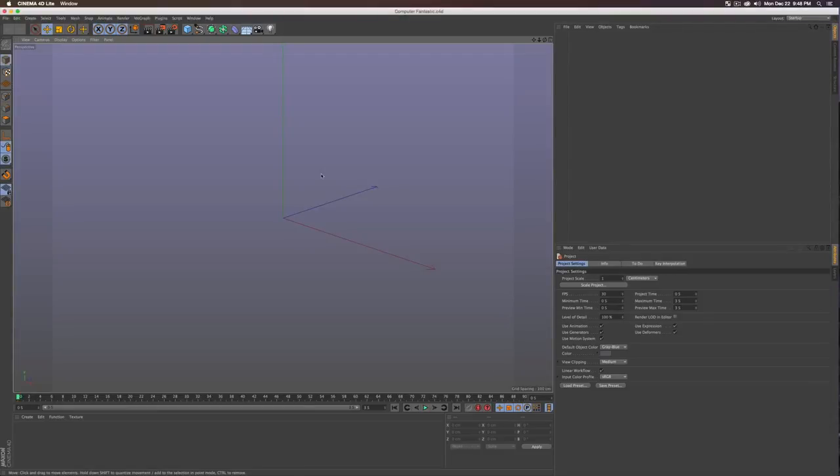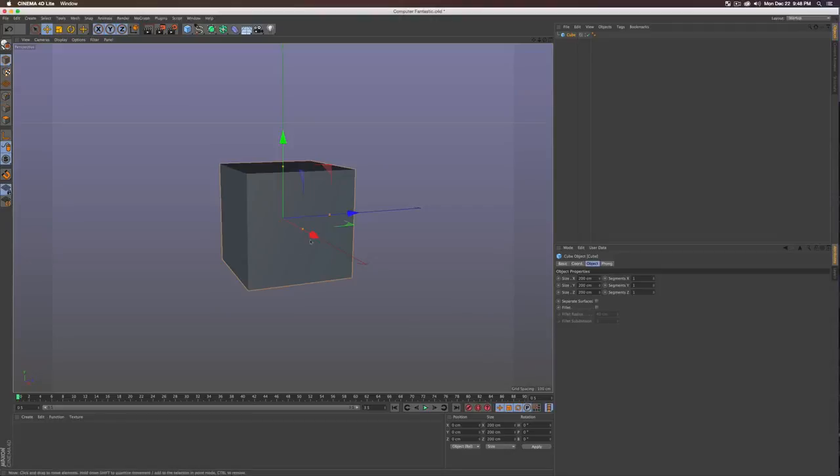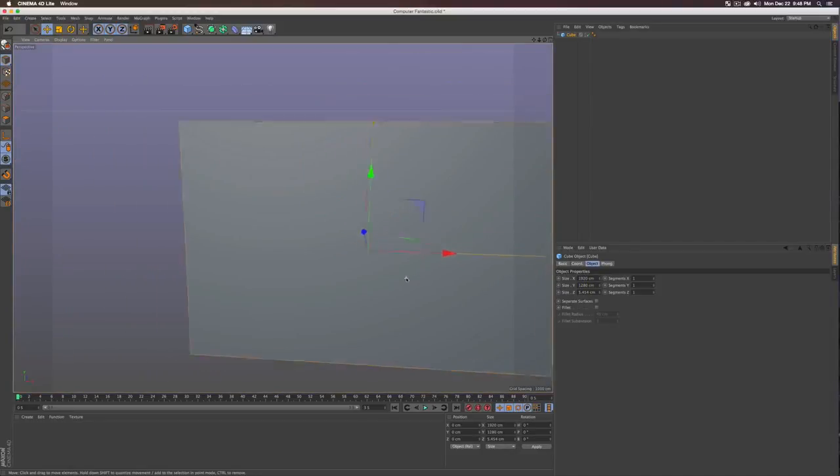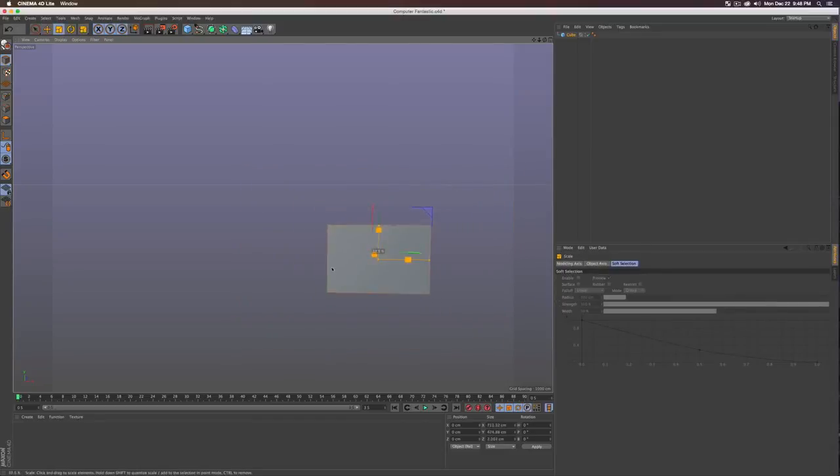And mine's going to open up in Cinema 4D Lite R16, which ships with Adobe Creative Cloud. You can also use Studio or anything else if you have a real version of Cinema 4D. But it's surprisingly robust for what it is. So I'm going to start by creating the computer monitor by clicking the cube up here and grabbing these little orange sliders into something relatively monitor sized, and I'm actually going to do 1920 by, I'll do 1280 actually, and this is just to get a relatively good size, and then I'll scale it down a little bit.